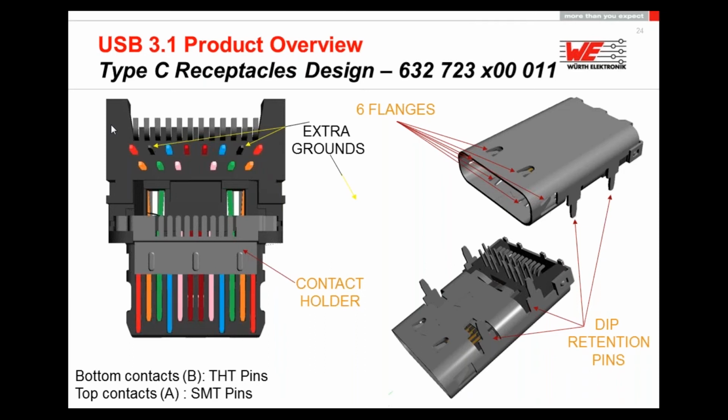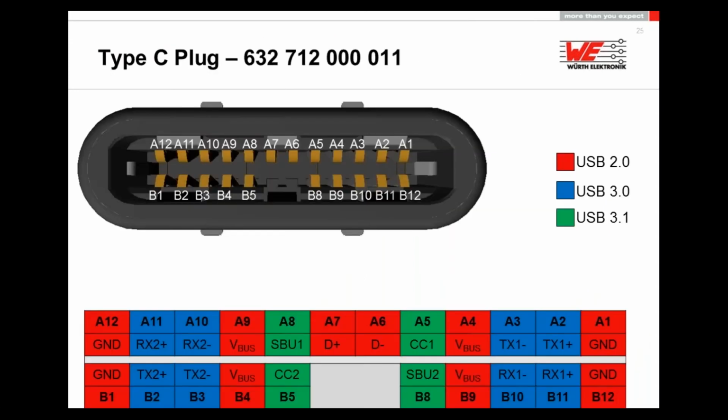And there's another point we can see in that picture, that we have different pins. So here we have the THT pins, and at the back side of that connector we have the SMD row of pins. So that is a part where we have a mixture of both, but that's important to understand, because this will also affect the way and the length of the conductor the signals are taking.